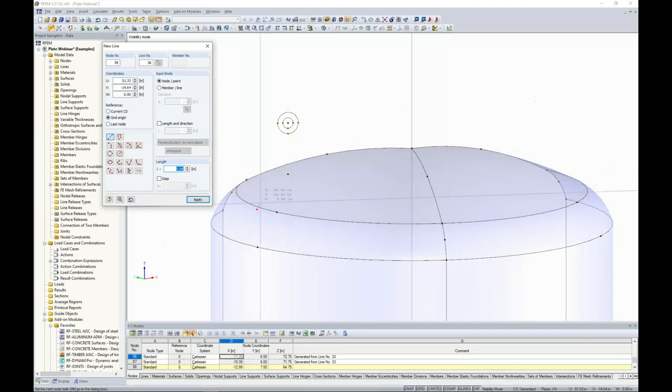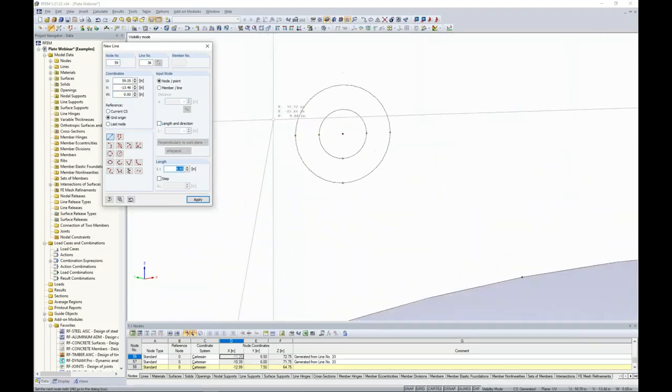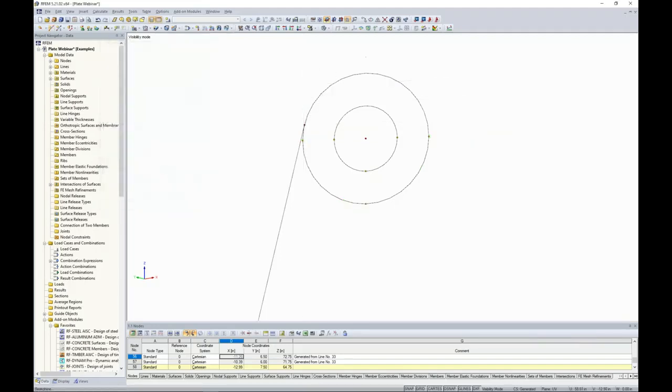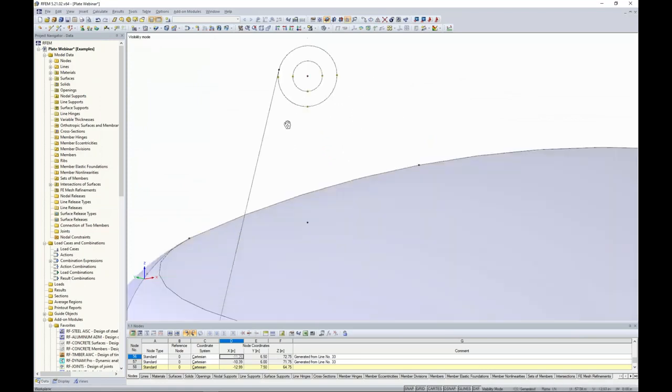I connect from the first point here and I zoom in, and instead of choosing this exterior point, I actually want the tangent point. And you'll notice that the program snaps directly to that tangent. And I can click on that, right click to exit. Now, the tangent point is controlled by object snap.